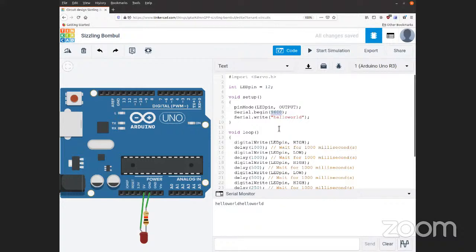That's just a random magical number. Well, it isn't. This number is supposed to specify the baud rate. Now, using serial, you don't have to know about the baud rate. All that you have to know is that the number in Serial.begin and on your serial monitor just have to be the same so they can properly communicate.